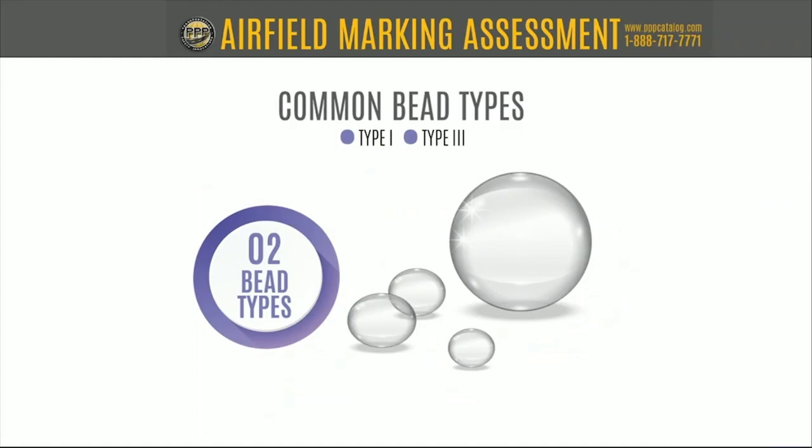One special note about type 3 beads is you are not allowed, prohibited by the FAA, to use or apply type 3 glass in red and pink paints. And there's a lot of backstory to that. I'm not going to get into it now, but just understand these are the most commonly used, and these are the ones that I endorse with my clients.